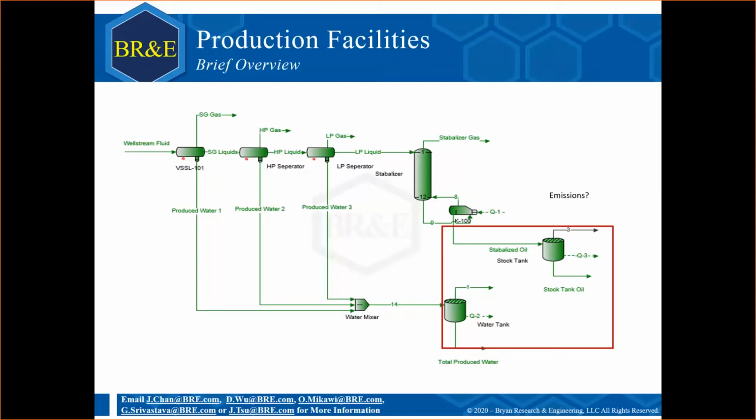That may not apply for how your local emission registry does their analysis. So I would take that into consideration. If your internal emissions are based off the US government's EPA standards, then the air emission tool will be fantastic in order to calculate the working losses. If not, then the basic ProMax thermodynamics, in particular the gas phase coming out of our tanks, will be more than enough to figure out the breathing losses from our tanks, just the natural losses to the atmosphere from the oil sitting there in the tank.